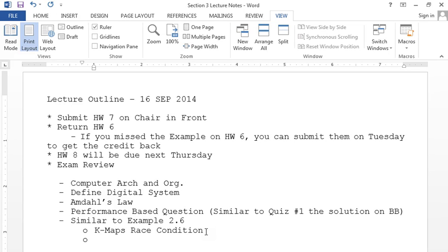So it's going to be a 3-variable question, A, B, C. And let's say I say do the Shannon expansion about variable B. What does that mean? Calculate the costs and do the total cost and then draw the circuit. Right. So when I have a 2-to-1 mux, if I say Shannon expansion about B, what does that imply about the multiplexer? B is going to be the select value. Exactly right.